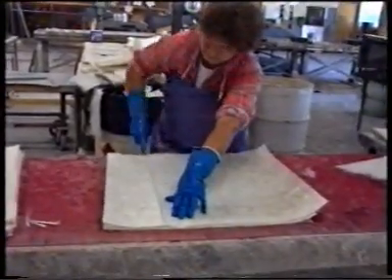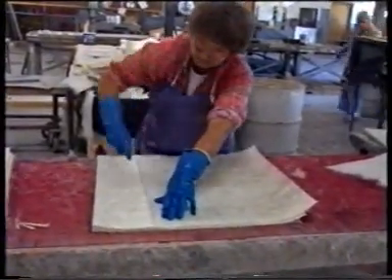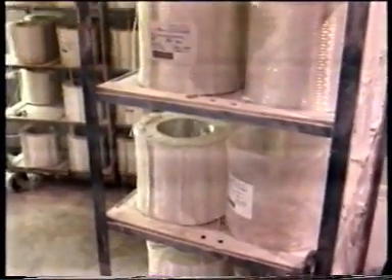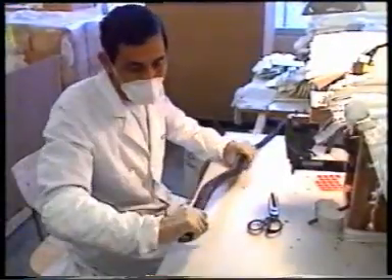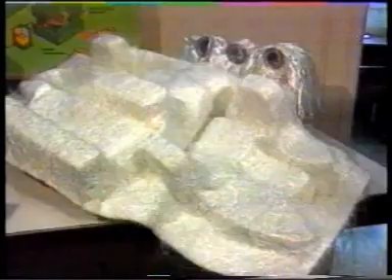These fibers come in many forms, with some of the most common being strand, tow, which is a continuous bundle of untwisted filaments, fabric, which is a woven construction of interlaced fibers, filaments, or yarns in specific patterns or weaves, pre-impregnated or prepreg tape, which is a flat, thin, narrow, and long grouping of parallel filaments held together by the matrix material, and preforms, which are reinforcements formed to various shapes prior to use.